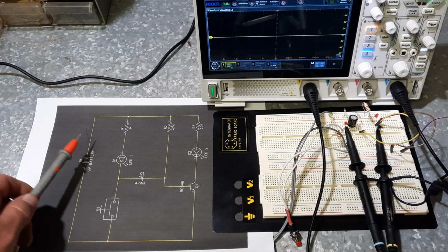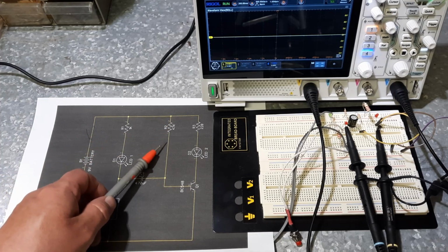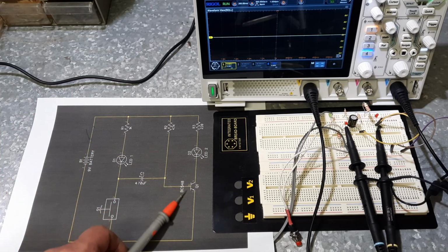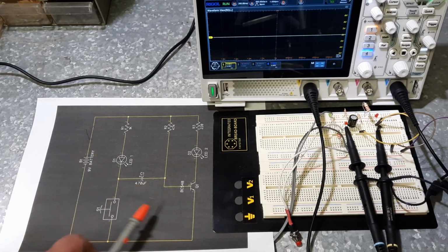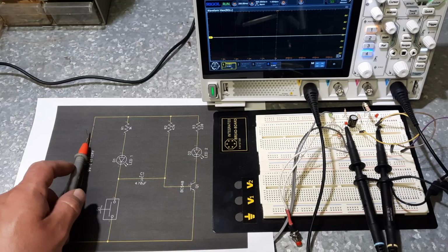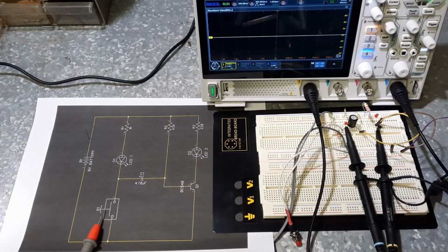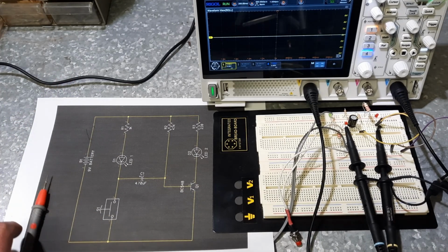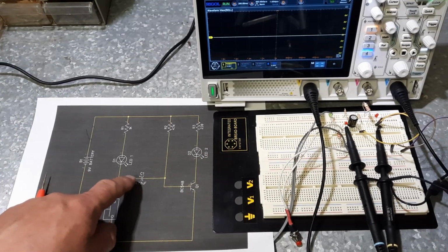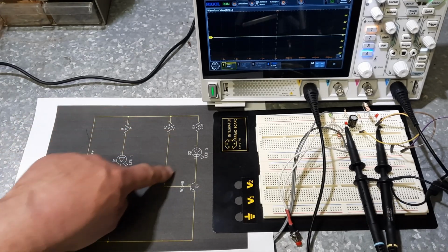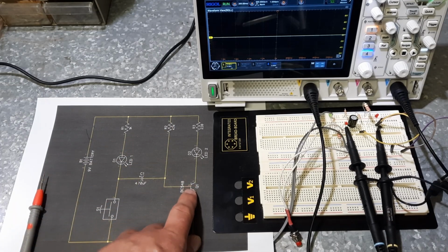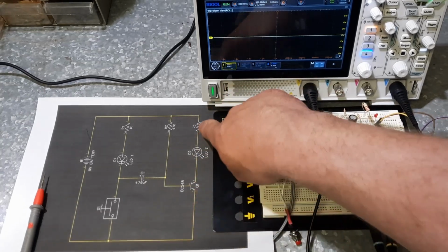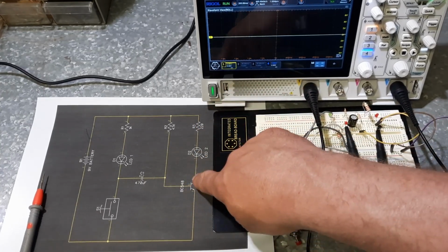We still have our current flowing down here, but it's no longer saturating this. What it's doing is equalizing this capacitor. So, like I said, imagine there's a switch here and that's still closed. We push this button, the current's going to flow from here and try and equalize. It's no longer going through the base to the emitter of this. This is in its cutoff region, or off, which means this part of the circuit is also off. It's open circuit here.